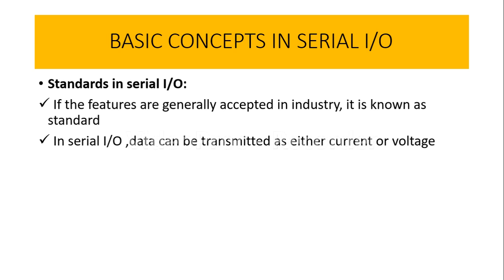Before seeing the concept of data terminal equipment and data communication equipment, let me tell you that the rate of data transfer in the RS232C is restricted to a maximum of 20 K baud, and it can be transferred up to a distance of 50 feet.